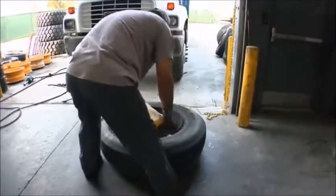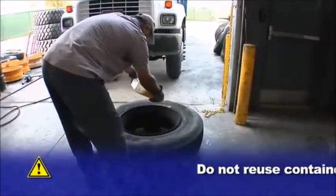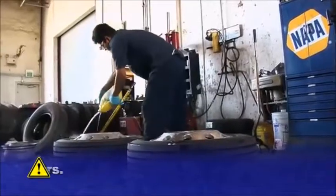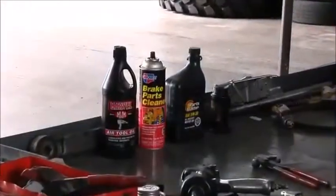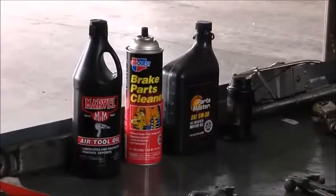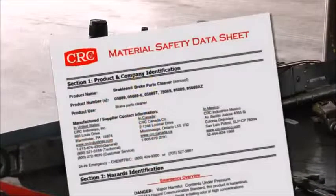It's also important to make sure that every container is properly labeled and that containers are not reused if the contents are different than the original product label. Once the list is complete, the manufacturer or supplier of each chemical is required to provide an MSDS sheet so technicians will know what to do in the event of an accident.